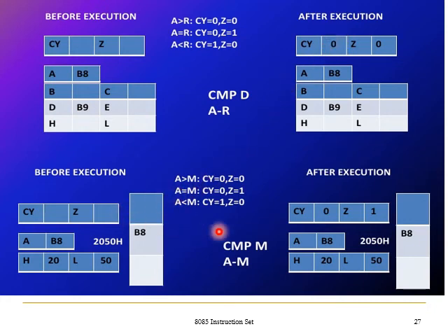In this example, compare M, the accumulator content and the memory location content are the same. If the processor subtracted, the result is 0, so the zero flag is set. By means of it, the microprocessor concludes that both the accumulator value and the memory value are the same, right?